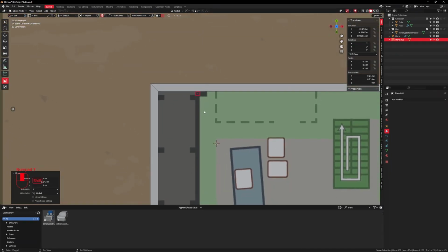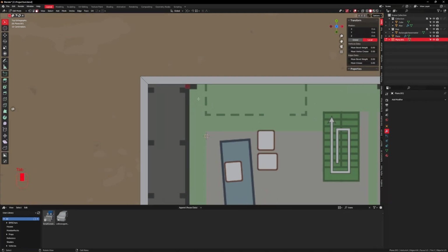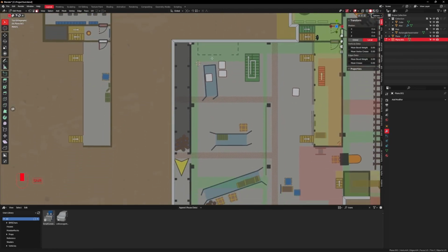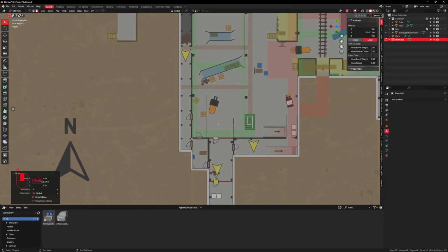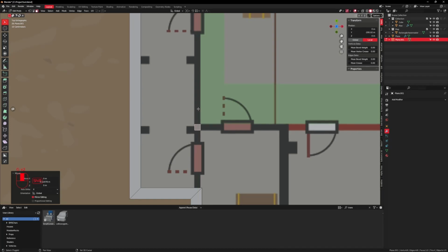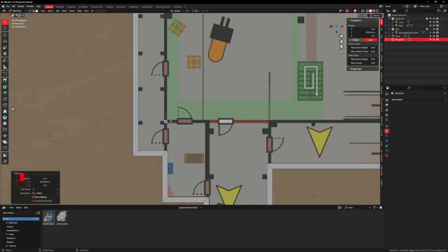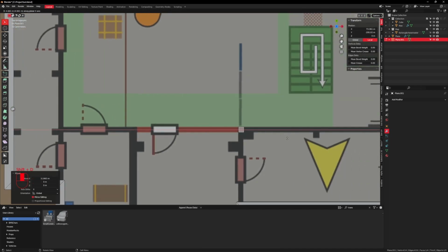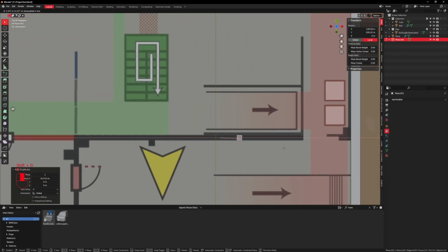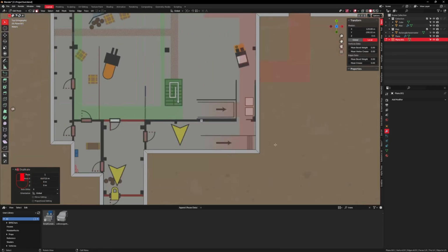Okay. Top-down view, go into edit mode with tab. Then make sure you're in face select, select that square there. Then I'm going to press Shift D to duplicate that part of the mesh. And the same way, use the G, middle mouse, and move this downwards until the walls cross each other here. And basically, you want to do this for every single corner where two walls meet. So here and over here. Here we're going to use the snapping again, holding Control.